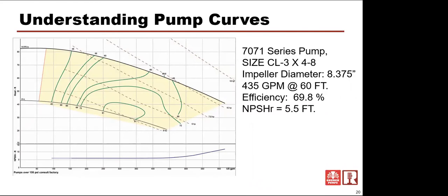The ability of us to accurately size this pump from a pipe system engineering standpoint is good, but not exact, unless they really went to great lengths to try to pick it. If they say they want 400 gallons a minute, it's probably not going to operate at 400. But the bet is it's going to operate somewhere else.